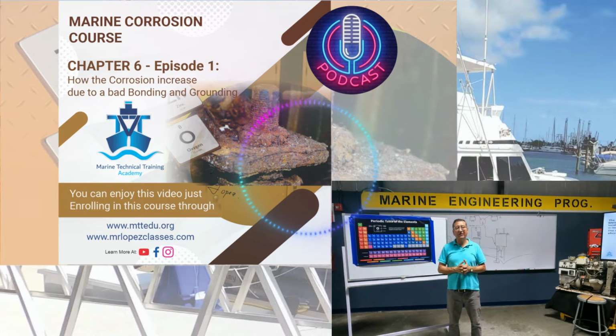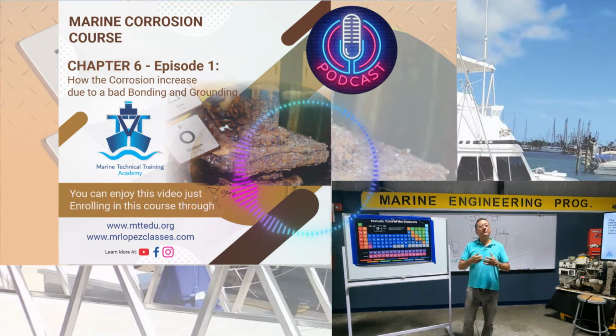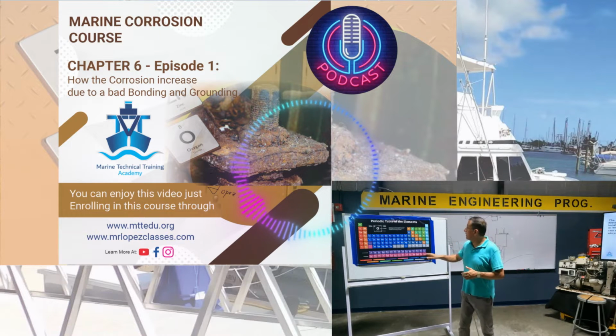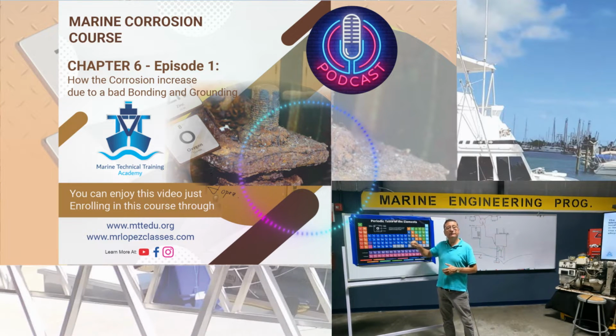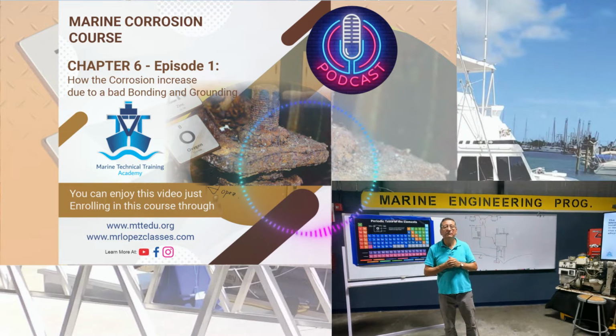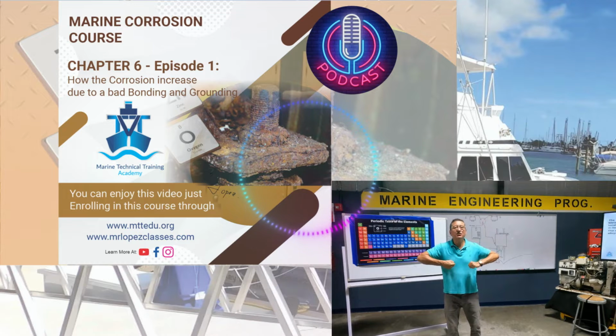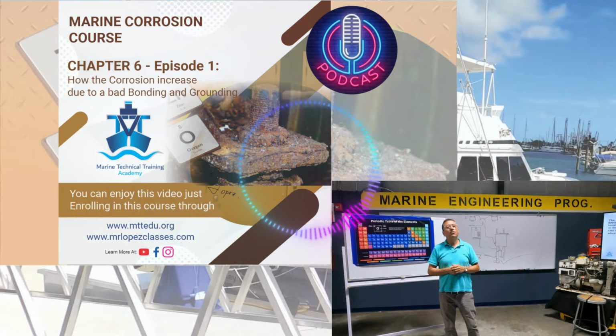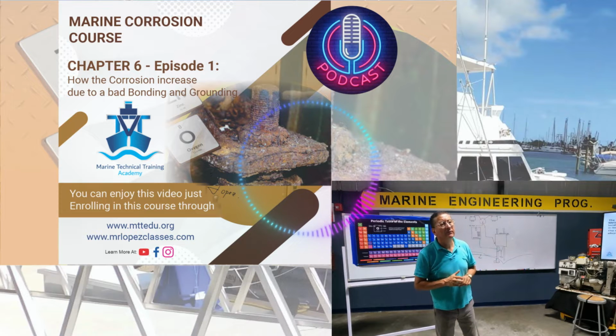In other words, if I have a boat only with DC current, a small boat, those boats are less prone to corrosion. When I introduce AC current in my boat, when I introduce an AC panel, battery charger, and other equipment, shore power and pedestal, my corrosion problems are accelerated. Yes, my friends. And no problem, we are going to analyze the process to identify where the leaks are.